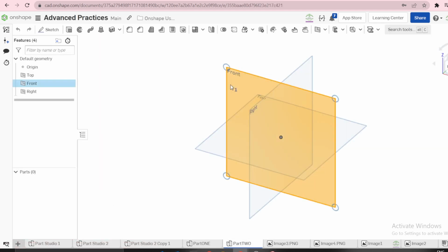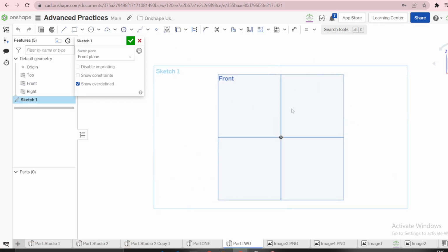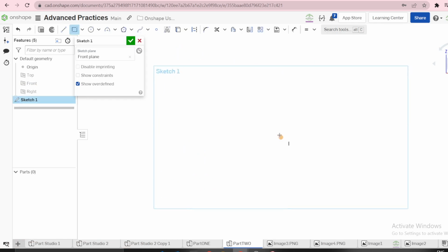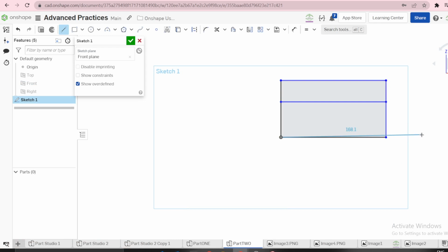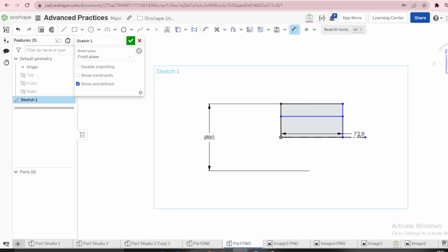Therefore, you go to the front plane, sketch, normal to you. I'm going to use P to hide planes. Then I need a line. Then a center line for construction. Dimensions will be from this point to this line to be 80. Then from this point to this point to be 50, like that. Then the length is 80. Length is here 80.